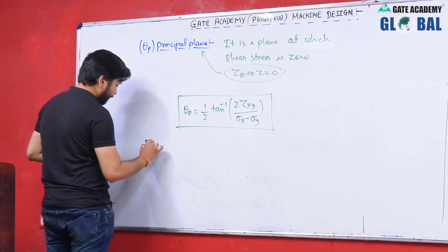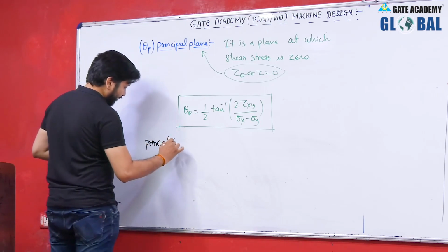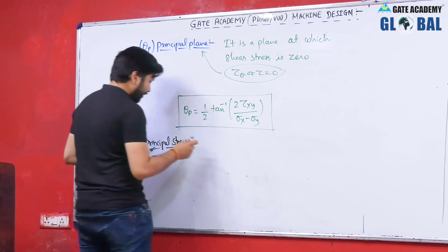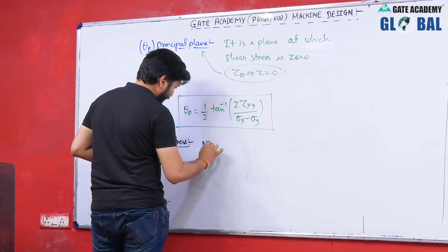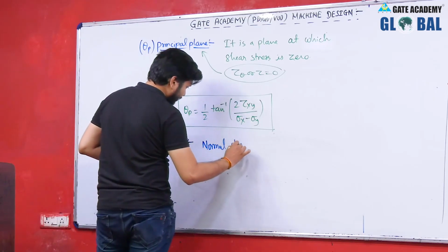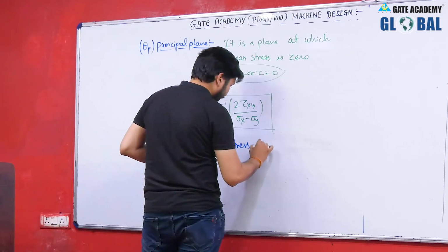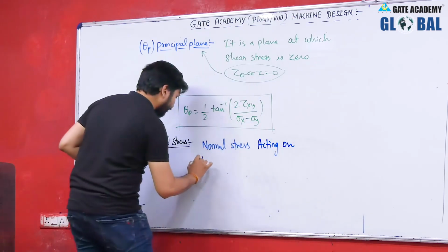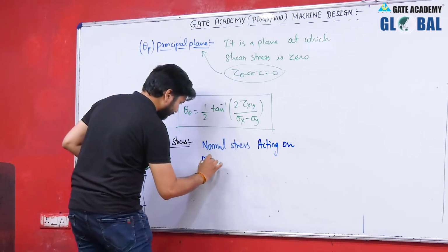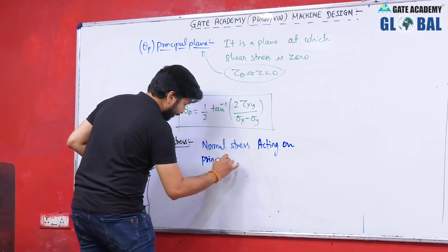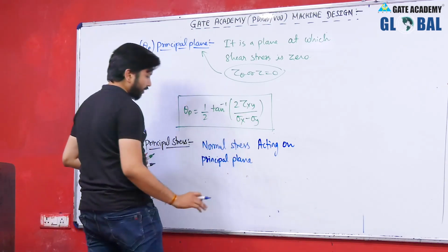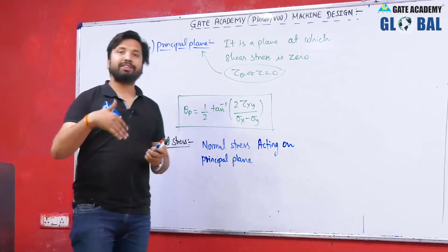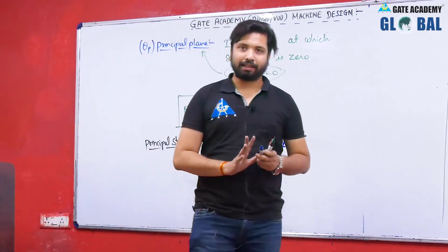So principal stress, that is normal stress acting on the principal plane. Now if a loading is 3-dimensional loading, then there will be 3 mutually perpendicular principal planes.